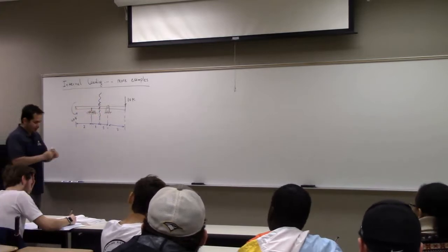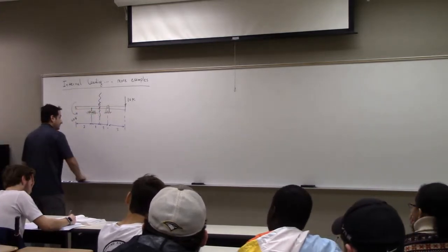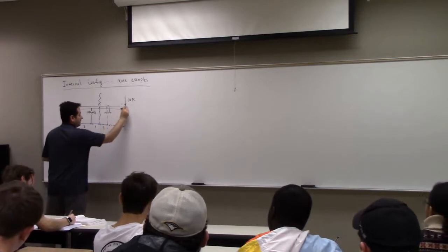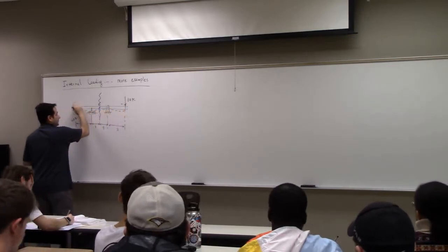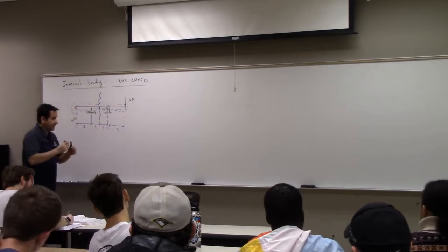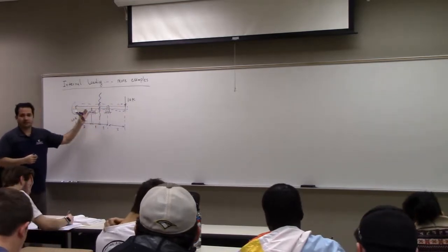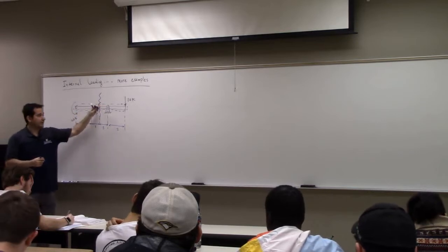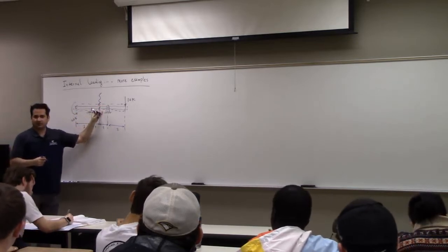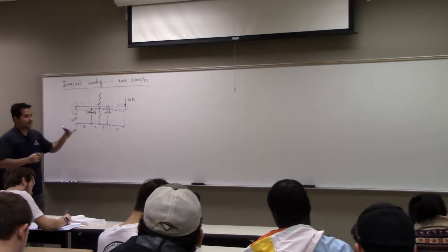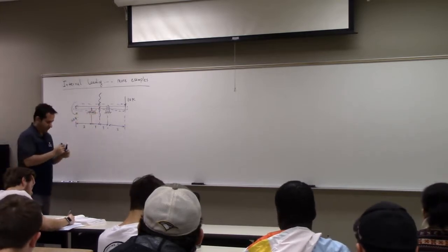So before that, I take the entire thing as a system to find external reactions. And then once I get these two, I either take the one on the left or the one on the right, and then I can find three components right here, right? Then I repeat this example for some other points.